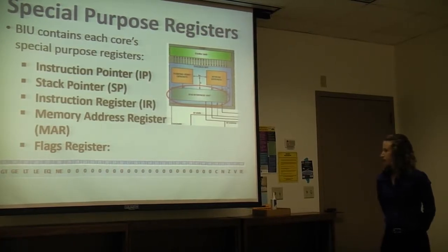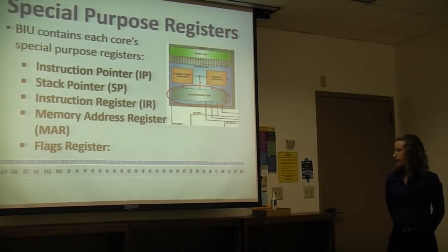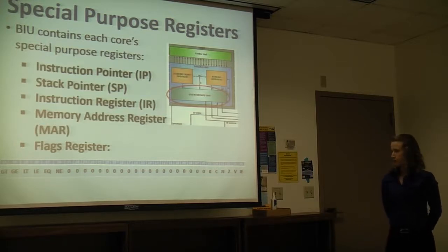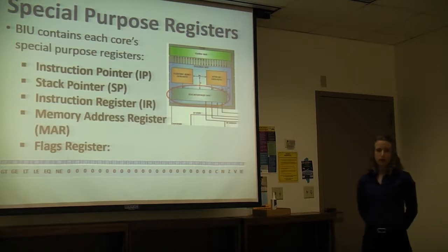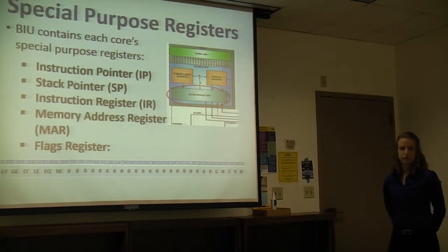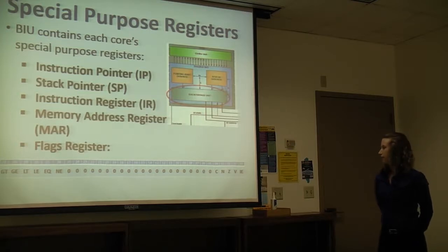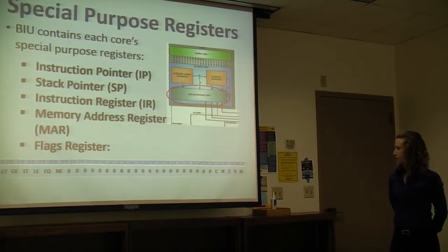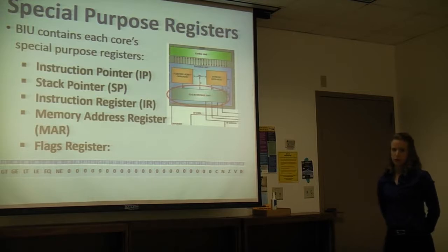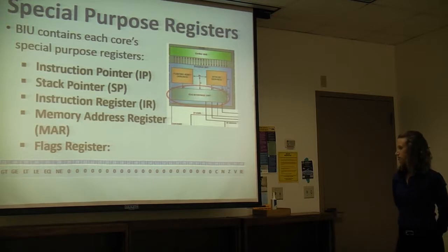Our least significant bit is our interrupt enable flag, which is set in software by the interrupt enable instructions. Each core can have the interrupt set or cleared, separate from each other. And then we have 4 flags for the integer data path, which are set with logical and arithmetic operations.